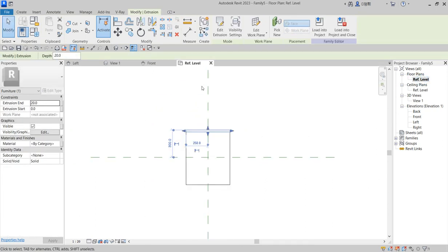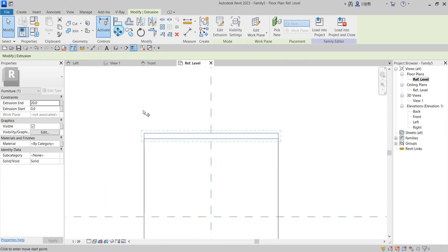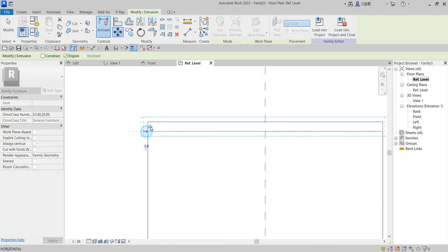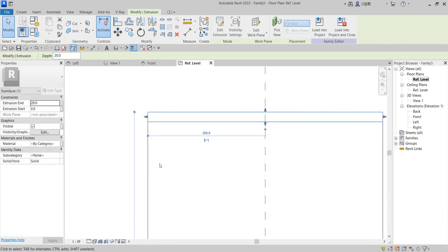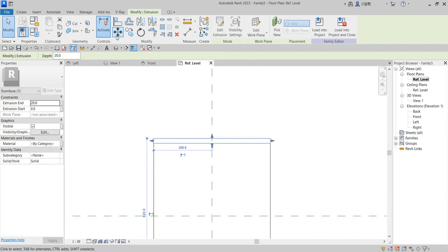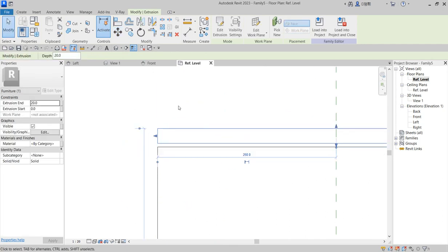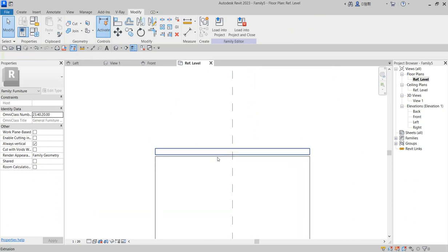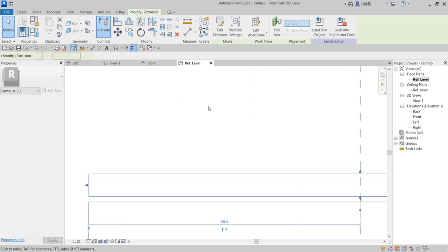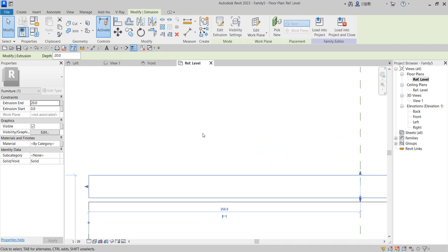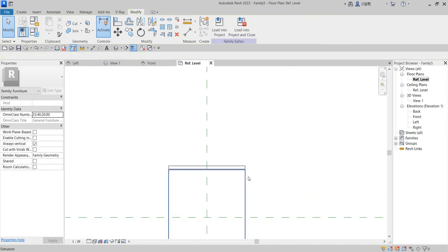So this is where your front is at this side. So what you do is shift this a little bit backward to the next side. So you can decide to open it a bit, like 5 mm. So click there. Good. So that's giving the space in between. So you can adjust it a bit by pressing the arrow key and see how far it goes.